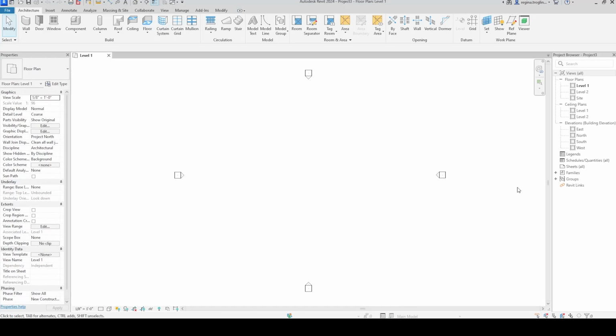Now, as you can see, everything is lined up. A lot of times, Revit's default has this project browser down at the bottom left in these panels. I prefer to keep them on either side. It makes it easier, especially in a commercial project where you'll have 5, 6 to 10 floor plans, sometimes more, with their ceiling plans, elevations, sections, all of that. So this gets very, very long. So having it over here just means that I can see things more easily.